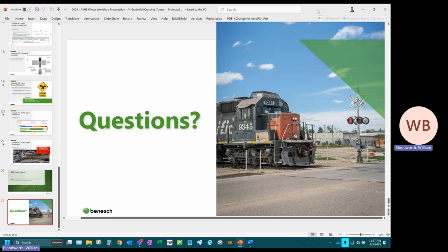It's my favorite off-system safety funding thing, I think, because it's within the right of way. Primarily those off-system safety projects have to be within the curb lines. They handle resurfacings as well, just right of way and utility coordinations. The main ones, you might have to pull out the flashing beacons depending on solar power there, because you might not be able to get utility over there. But at least you get a lot of those other countermeasures to do. I've been working with off-system safety lately, and those are my favorite countermeasures to give to them.